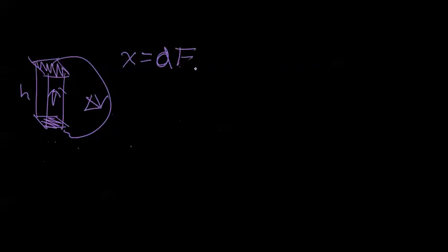So when we are this time applying an electric field, how do we do that? We apply a certain voltage across the two surfaces. Therefore, an electric field is generated within the material with regards to the distance between the electrodes, the thickness of the piezoelectric material. And we generate a displacement this time, which we can see as strain. And this equation is used for actuation. We apply an electric field, and how much do we expect the material to expand and move? Mainly for actuator purposes.